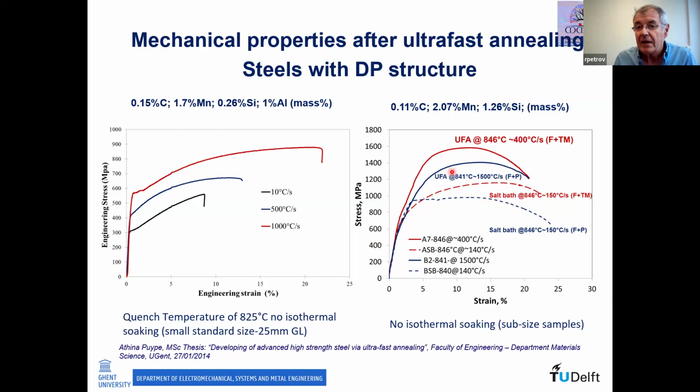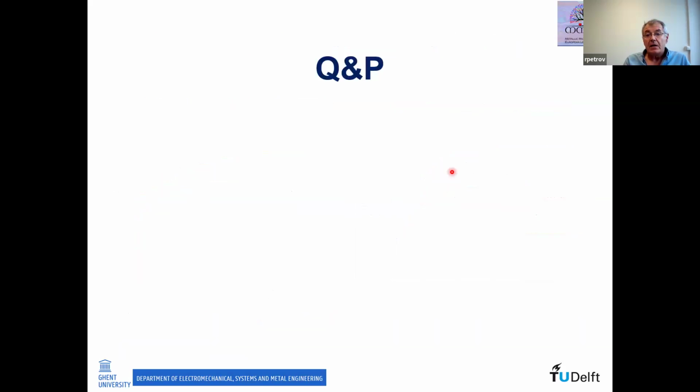It can be used to control. Is it logical? I think yes, because the initial microstructure shows you the distribution of the elements which will diffuse at high temperature and will form your austenite. And because the time is very important here, this is of critical importance also: what kind of initial microstructure. Practically, it means that if you'd like to have good results, maybe you should start your heat treatment after a heat treatment already done before. A few examples for quenching and partitioning.